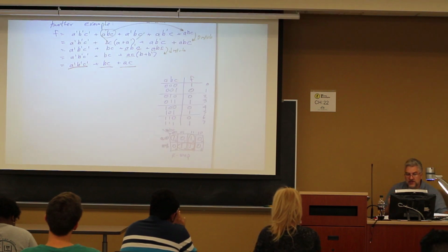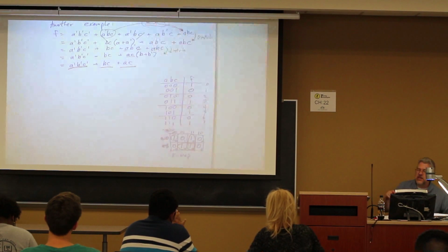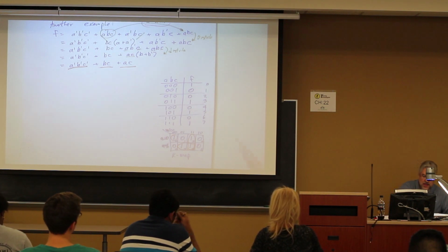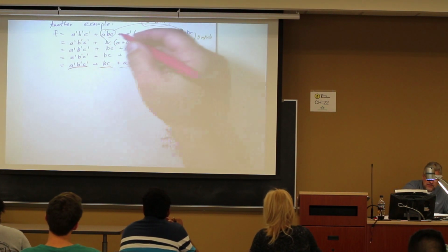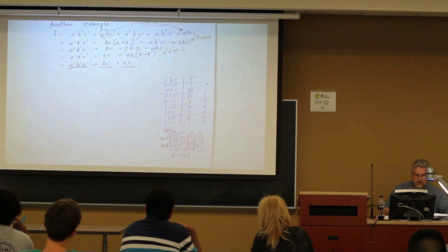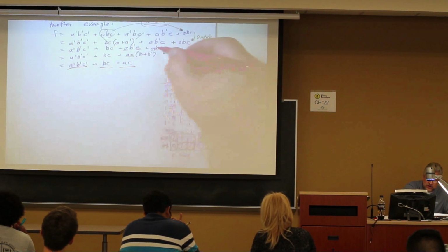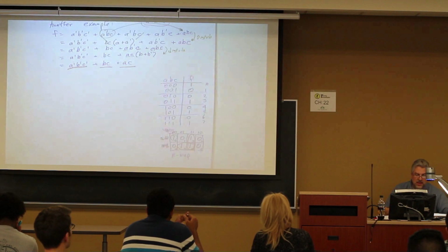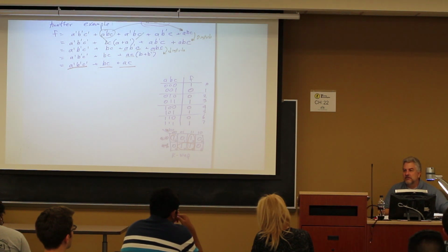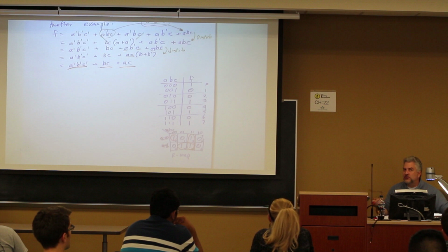So in the process of this, in the Boolean algebra, I knew that by using the idempotent, if I got that right, by adding in another of these A, B, C's, remember A is equal to A or A, then I could combine these two here and simplify my equation. Now, was that cheating? What do you think? It's another tool that you have.